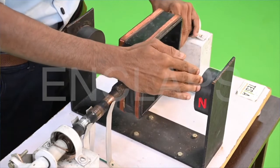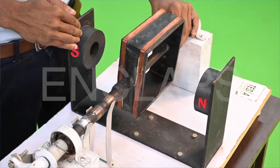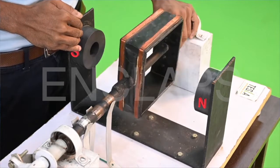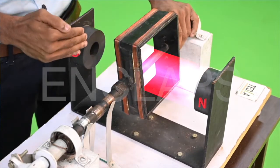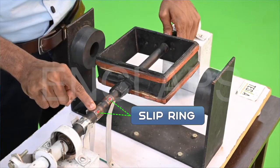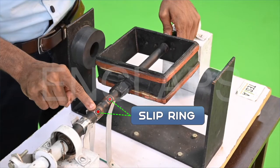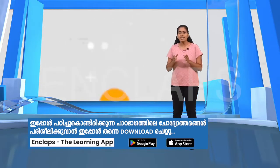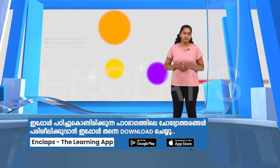This is the north pole and this is the south pole. We know that the magnetic field lines are always from north pole to south pole. These magnets create a strong magnetic flux inside the generator. Slip rings are the other important part of AC generators. These rings are finely touching the graphite brushes. But it is very important to note that the brushes and the rings are not connected together.